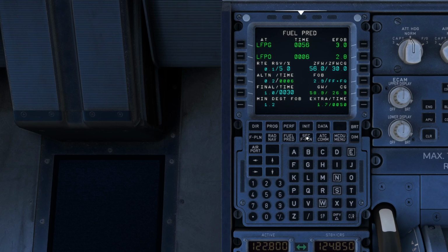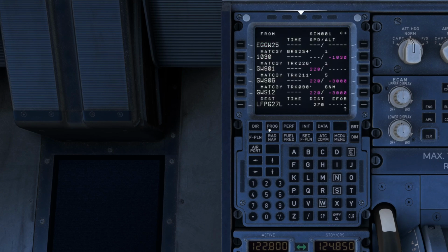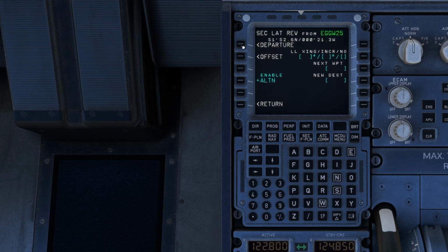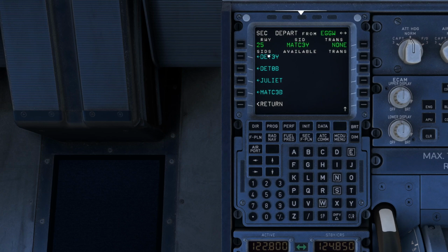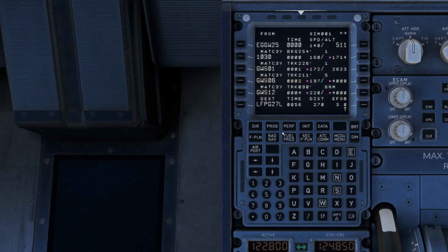Once again, this can change depending on your final figures before you get going, but this is just the basics of the fuel page. Secondary flight plan, generally in our airline we would copy the active. I'm not sure if it's going to work on the flight sim. We go back into here, departure, press the right arrow, and here we would have an option for an engine out SID. So this is our contingency procedure. If we depart and we lose an engine, once we're in the air, we'd activate the secondary flight plan, and this would activate our engine out procedure, tell us which hold to go to, to work through the problem. So that's not available at the moment. And that's it really, guys.